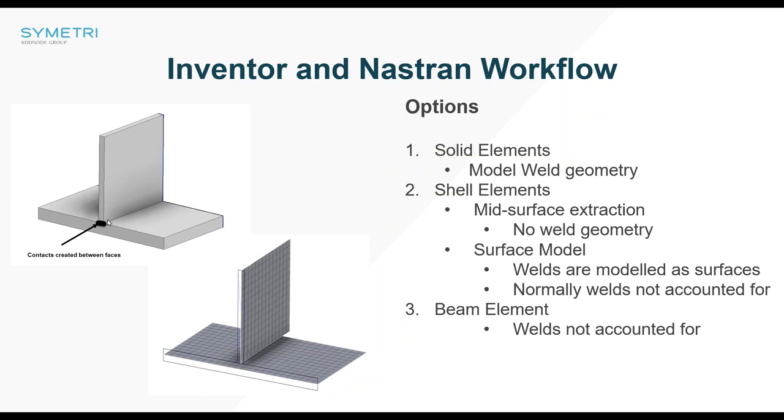Whereas in real life, when we're doing welded structures, it's primarily that contact remains free and we have contacts on either side of the plates, or maybe even one side of the plates. Now, if you were to idealize that using shells, then the problem becomes a little bit more difficult, because you end up having gaps between the plates, and then there's no way for us to put welds on there. So we'll have a contact between the bottom of this vertical plate and one of the edges or the face of the horizontal plate.